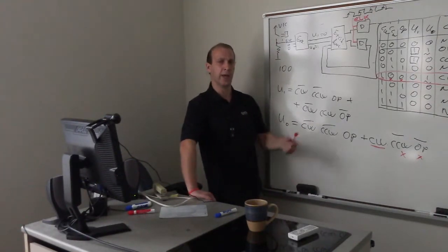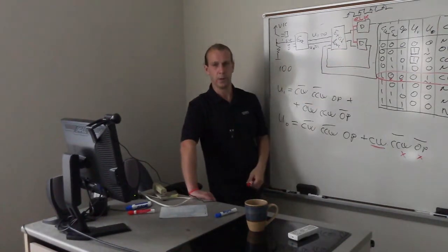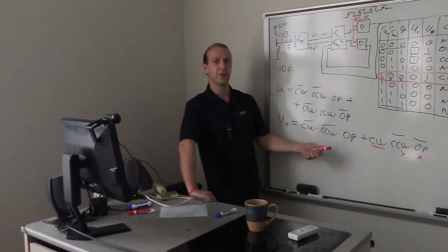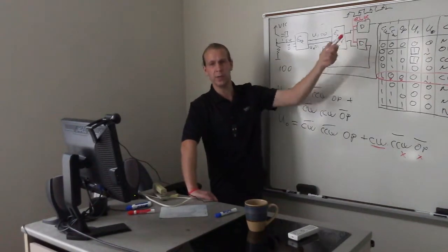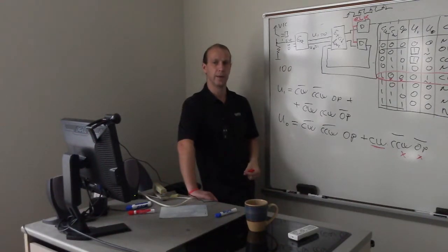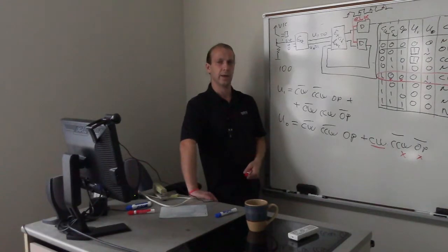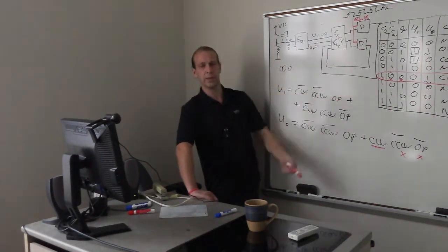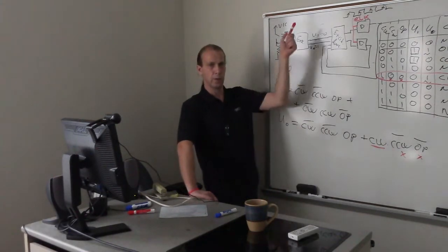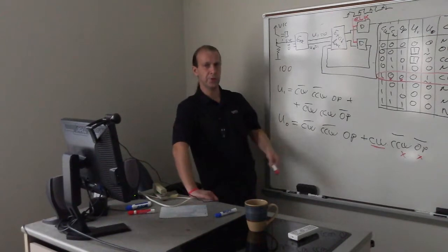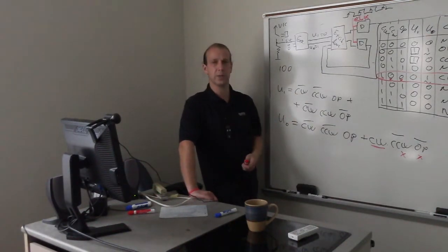That's up to us to assign a certain combination of 2 bits to a certain name. It is actually not important for design purposes. We can say the combination is assigned to state A, or we can say combination 1, 0 is assigned to state D. As long as operation of this finite state machine is purely symmetrical, we just go around the circle in one direction or another direction or across. It doesn't matter how we encode the states.